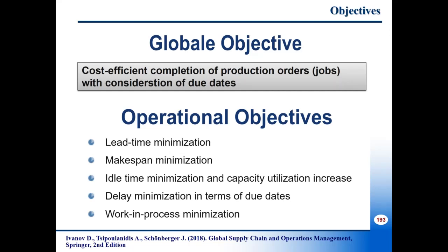The objective of machine scheduling is to minimize lead times that consist of all the processing time, setup time, waiting time, lagging time, and transportation time. Obviously, minimizing lead times needs a production floor to minimize makespan. Makespan is associated with a job processing sequence and is defined as the length of the period that starts with the release of the first job and that ends with the completion of the last job in the particular sequence.